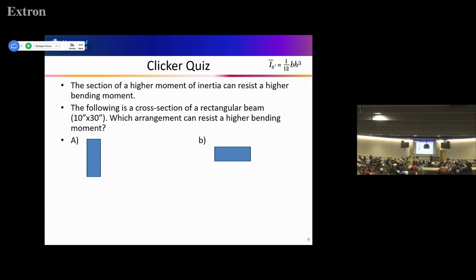And you can compare these two cases. The first one is this configuration, and the loads are here, okay? Here, right? And then I try to bend my folder, but it is very hard to fold, right? Higher moment of inertia, higher resistance to bending moment. And then the second case is this, using this cross section as a beam, right?